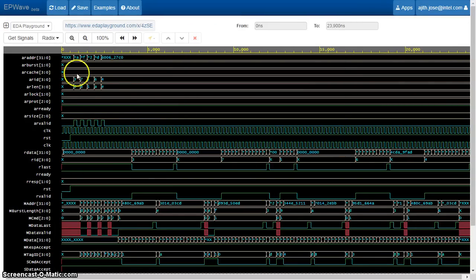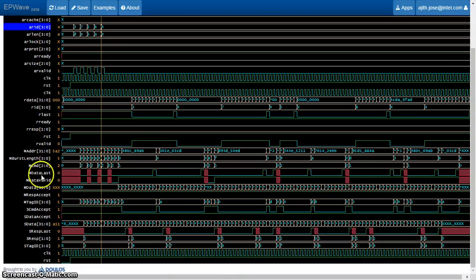You can see that these are read requests going through the interfaces. Here 5 read requests are generated with tags 3, 7, 5, 6 and 4 with different addresses, and these are the lengths requested by the AXI client. You can see that these requests are going through the OCP channel at this point. There are a few more transactions injected into this DUT, so you can see a few more extra transactions here, which are coming through the other write interfaces and the second read interfaces.